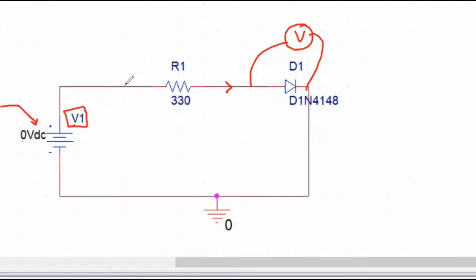We can do it, of course, in that way, but that is not the case. When we have the DC sweep, we can easily do a DC sweep. We can sweep this V1 voltage from some negative value to some positive value while doing the measurement in every node.